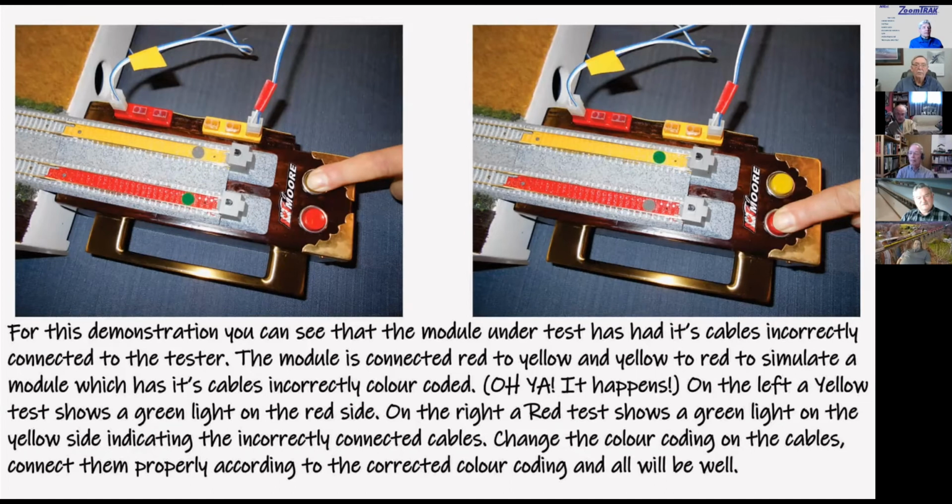On the left, the yellow test shows a green light on the red side. On the right, a red test shows a green light on the yellow side, indicating the incorrectly connected cables. Change the color coding on the cables, connect them properly according to the corrected color coding, and all will be well.